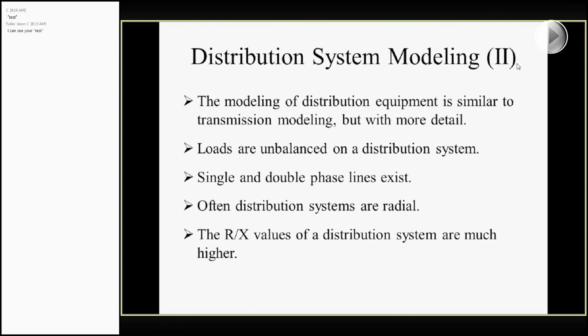The other thing to keep in mind is on the distribution system, your impedance values, so your resistance and your inductance, are typically a lot higher, and that's just the nature of the cables. You're not doing any of the things they do on transmission, like the transposition of the lines to help cancel out the magnetic effects, things of that nature. So your impedance values end up a little higher, so overall your losses are probably a little bit more than you expect out of a transmission system.